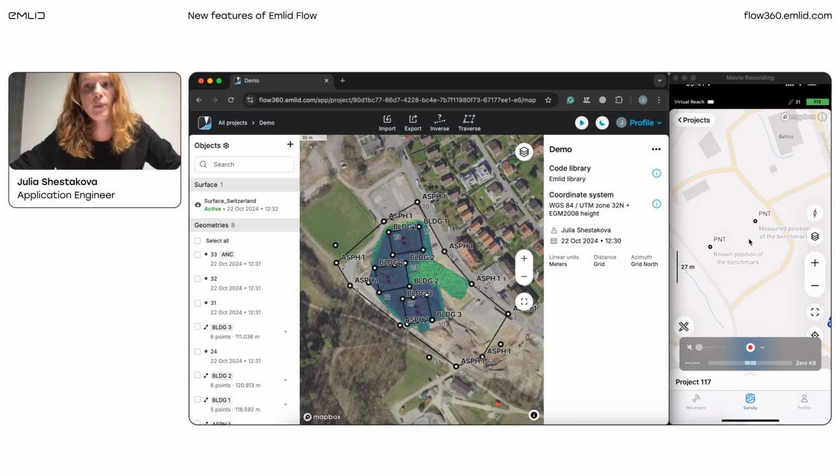So instead of that, I place my base in a good location and I average single its position. I connect my rover to it and then go and measure this point. As a result, I get the point that is different from the point with known coordinates, because my base was placed in single. So what I do next, I do base shift.